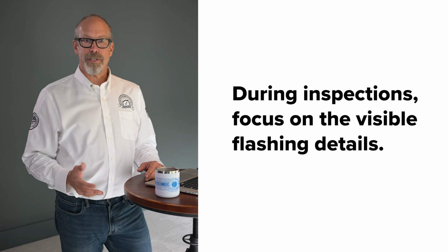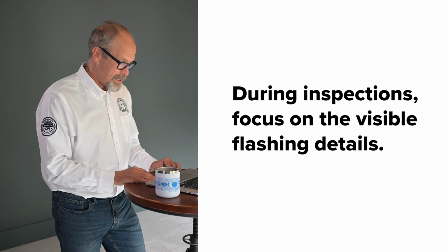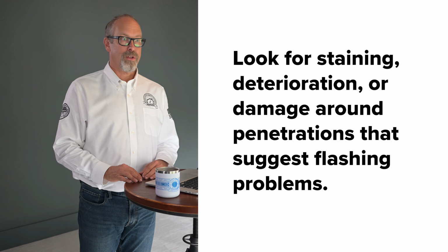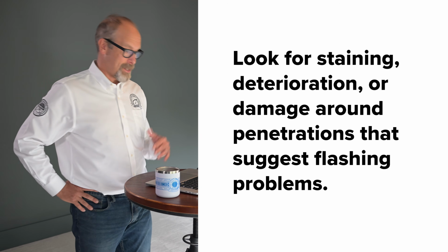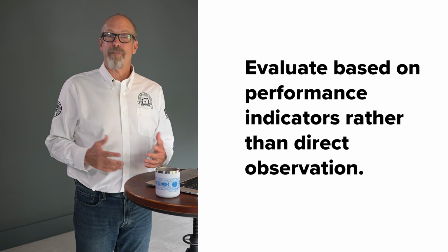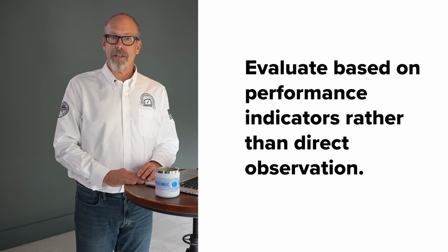So during inspections, focus on the visible flashing details and signs of water intrusion. Look for staining, deterioration, or damage around penetrations that suggest flashing problems. Remember that many flashing details are concealed behind the siding, so you have to evaluate based on performance indicators rather than direct observation. There are many viable flashing solutions for each application, not just single correct approaches.